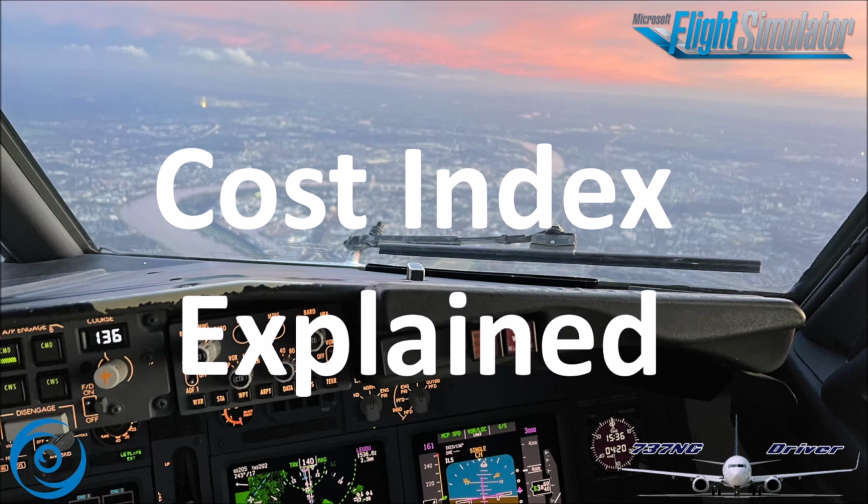Remember, that is the highest cost index available in the Boeing 737NG. Now, my airline's flight department has said that the highest cost index we can ask for is cost index 100. And that is normally giving you speeds in the region of, in the climb, maybe 20 knots below VMO. Then in cruise, you're normally somewhere around Mach 0.8 with it, so you just have a very tiny margin to the top. And then in descent, it gives you something around 320 knots. So once again, a little bit of margin left, but not a lot.